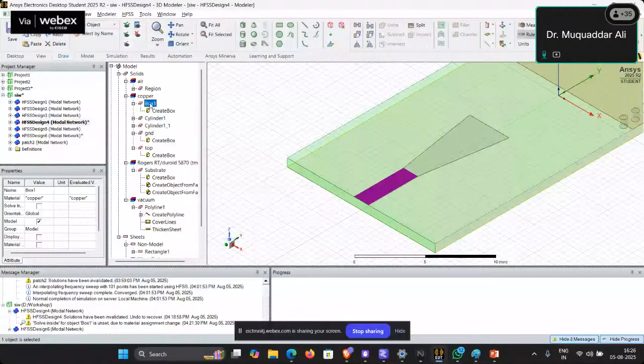Here we will be connecting a wave port. Up to this point, the length and width of this microstrip line correspond to 50 ohm, and from here it is starting to flare. And at this edge, we have the impedance that is matching our waveguide impedance. Okay.